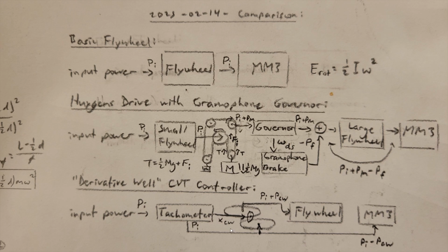Due to the way the CVT is set up, it is virtually impossible to exceed the target speed by a certain percentage because the flywheel would be able to absorb that energy almost indefinitely. Likewise, it would require a dissipation of the entire energy of this flywheel in order to decrease the speed by the same percentage below the target.